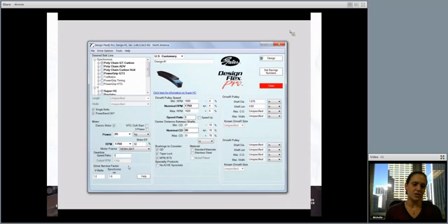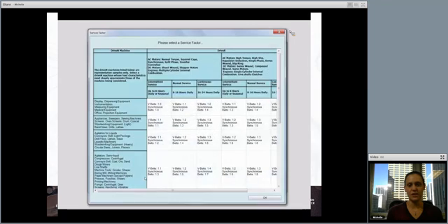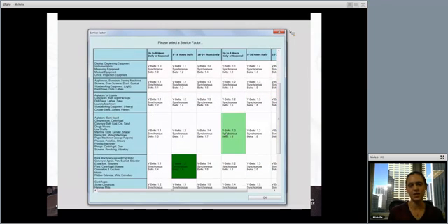With no gearbox, you'll put in a service ratio of 1. And then for service factor, you can go to help, and then it actually has a chart where you can pick your application, hours per day, and startup load, and it will set the service factor for you.